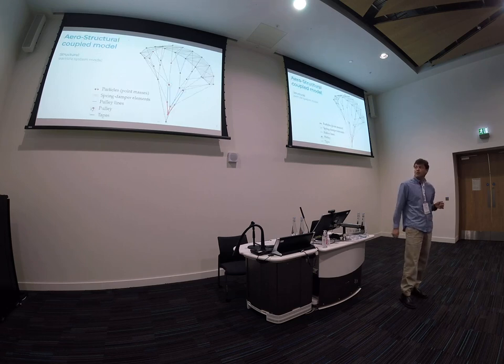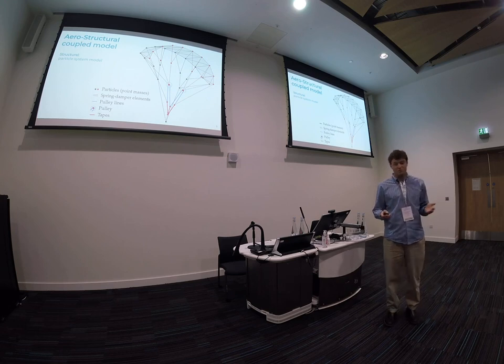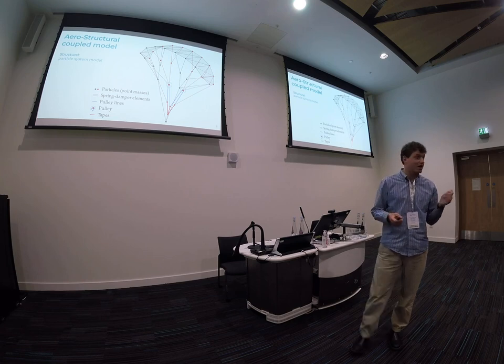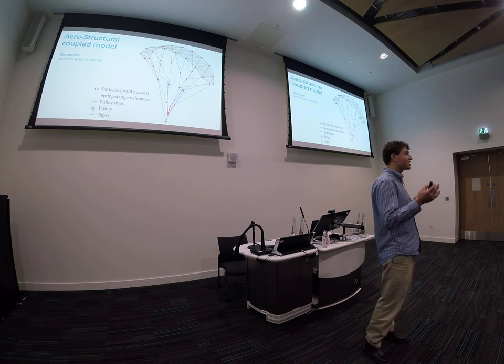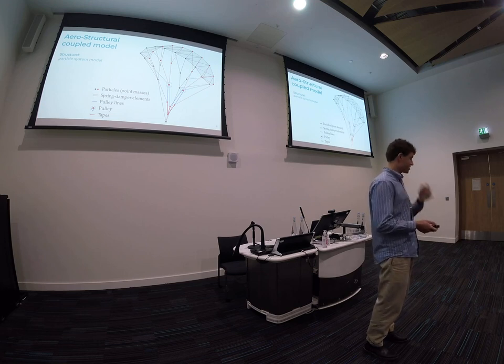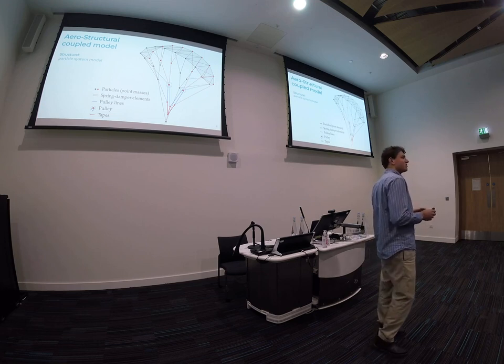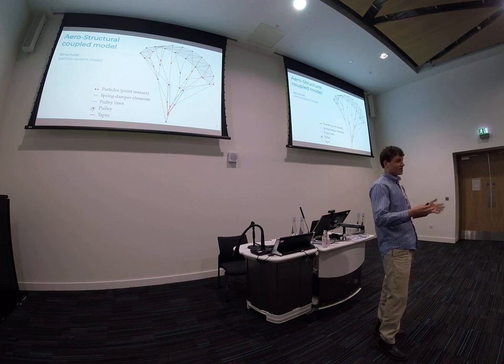Alright. So we need to build an aerostructural coupled model to take into account the actuation-induced deformation and the aerostructural coupled deformation. And ideally, we'd like to simulate those both at the same time. So we need to include the steering and depower tapes. You can see the tapes here. Some efforts have been done in the past to develop a very high fidelity fluid structure interaction model, or aerostructural coupled model. I tried to do it differently, more on the low fidelity side.